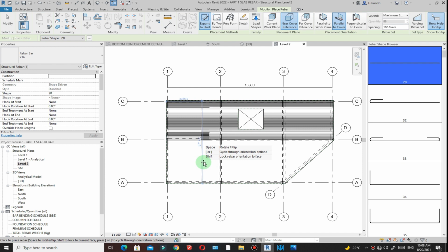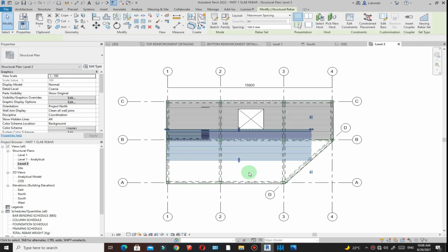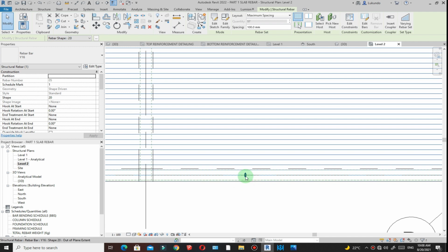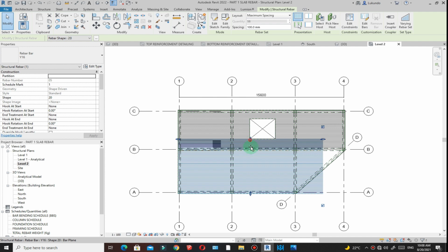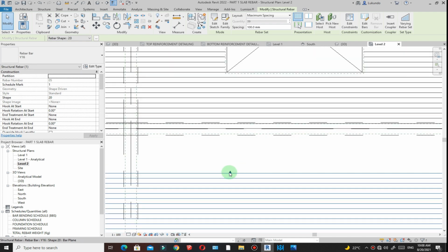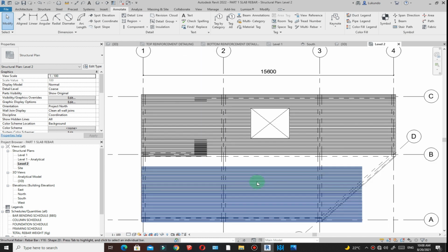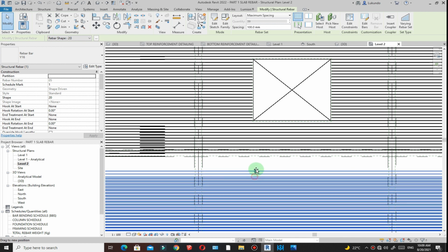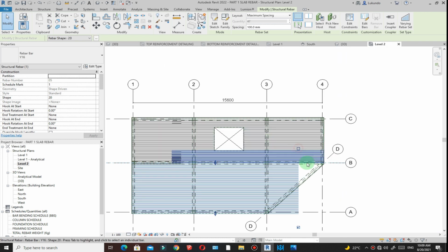Then make sure that space bar there. Okay, so I'll just place it there, click on modify, just click on the rebar set there, drag it all the way until it snaps up to the cover there, as you can see. Then drag it down. Let me just activate the tick so that I see where I'm supposed to end my rebar set. Select on it, then drag it up to there. Make sure that you deactivate the last rebar.